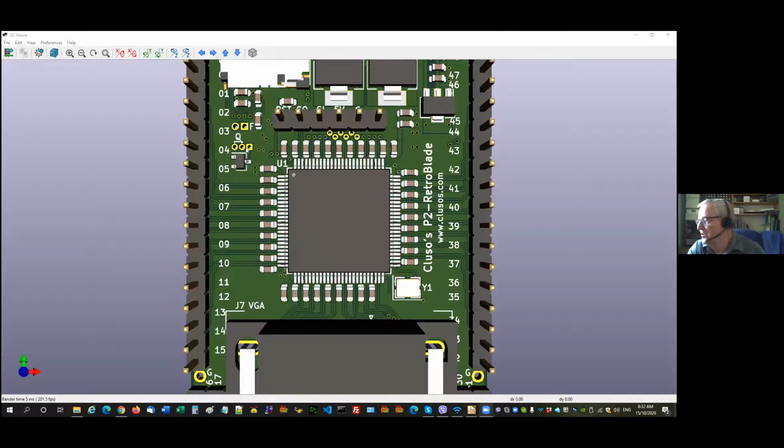Now, if you're always going to use a cheapy USB serial, great, you can link it by just linking the board directly with a little solder bridge. But if you want to make it optional, you can use the little 3-pin header and shunt.